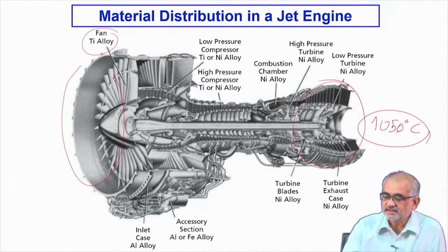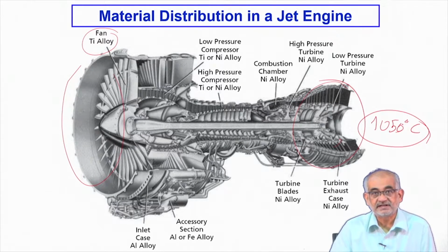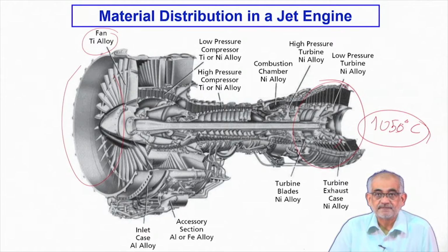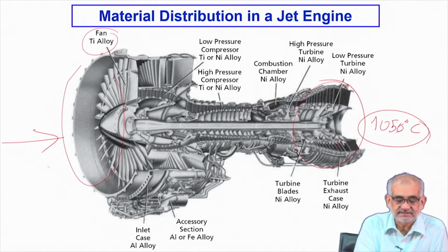So obviously at this high temperature, for the nickel-based superalloy turbine blades, the biggest threat one has to take care of is oxidation at the very beginning. Then come all the others, like high temperature creep or high temperature strength requirements, to prevent erosion and various other processes. So these are all surface damages. Even on this side, when you are sucking in air, along with the air you may suck in a lot of solid particles.